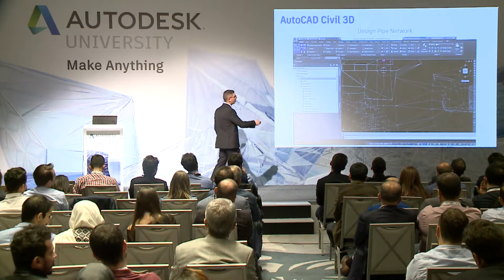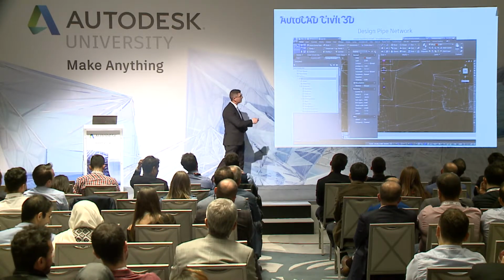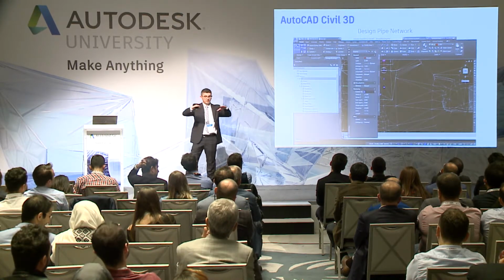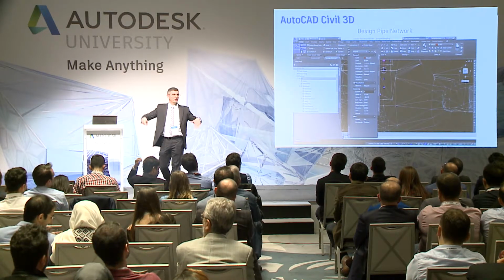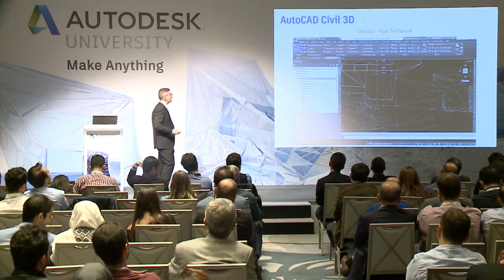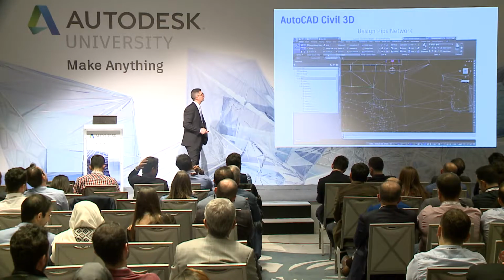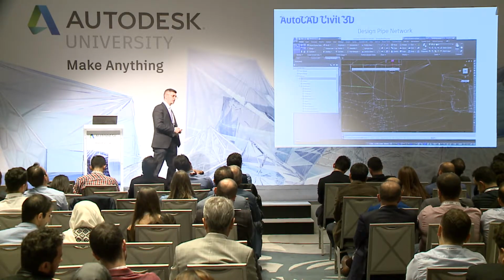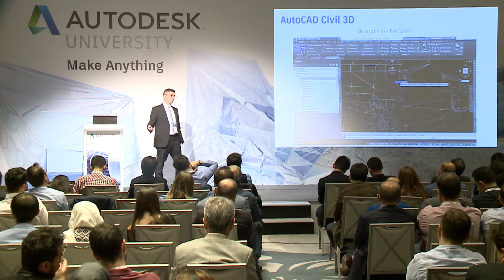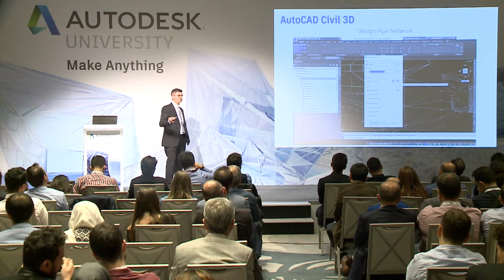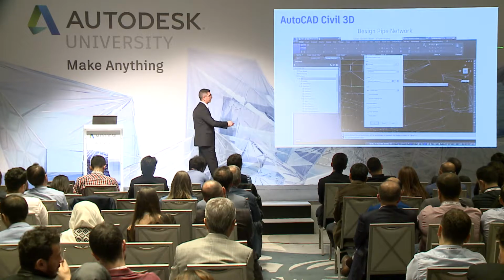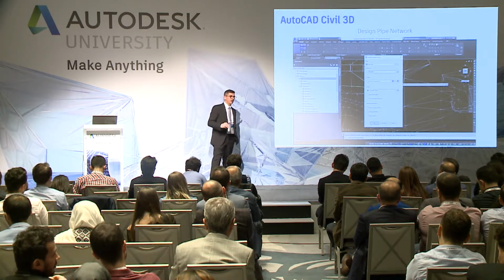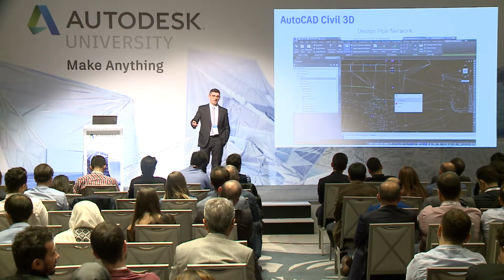Then I would like to convert this polyline, that is flat because it's an AutoCAD polyline, into a sewage system. Again, I would like to start from a feature line, because a feature line is one Civil 3D object that allows me to convert into other objects. The first step is take the CAD line, convert to the feature line.